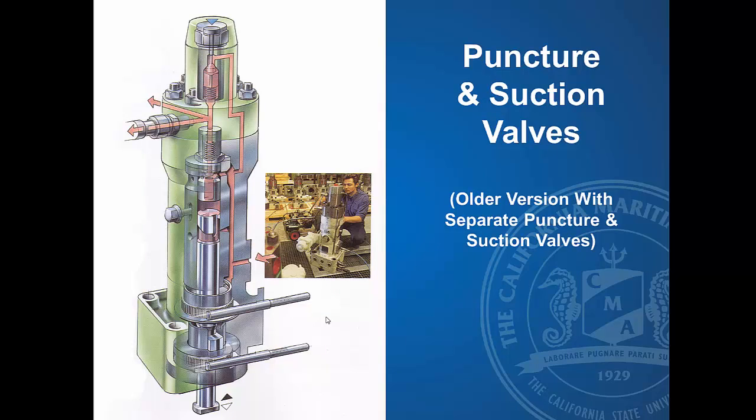So again, on this you have the rack that moves back and forth. You have a control sleeve, a threaded barrel, and that will move that barrel up to retard timing and down to advance the timing.